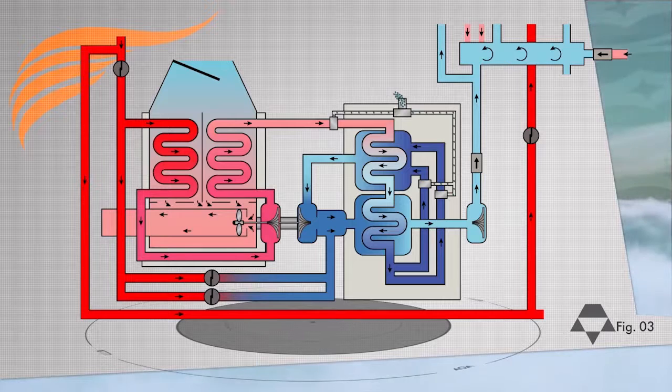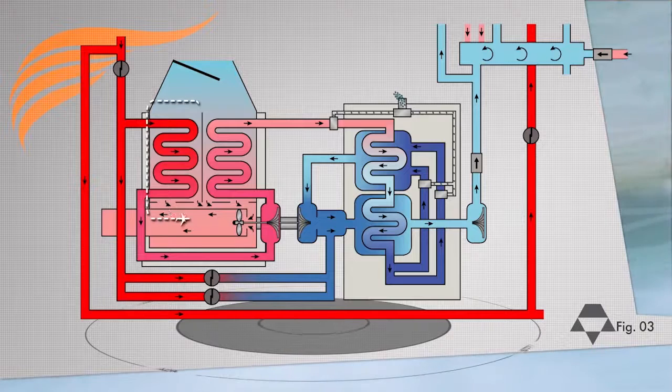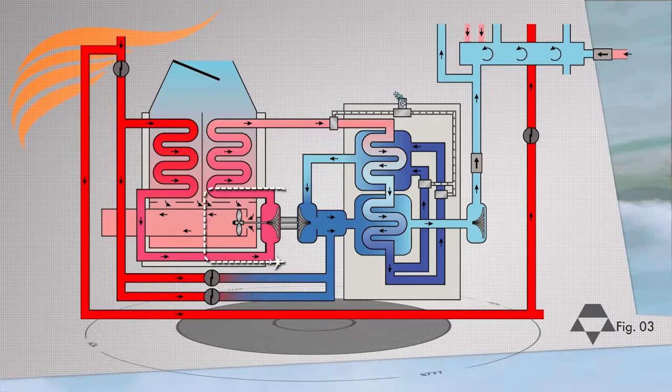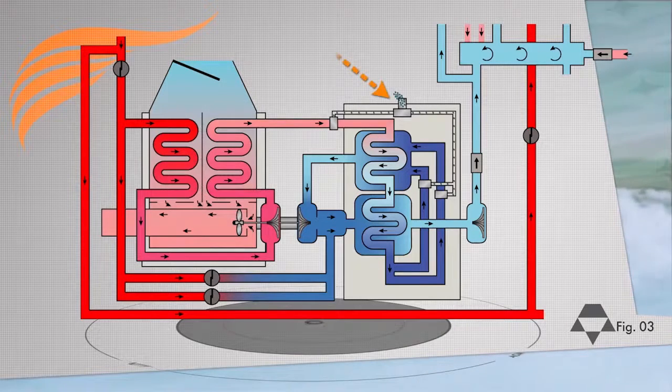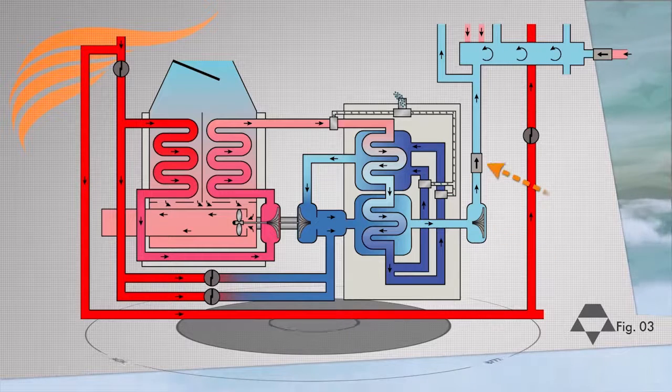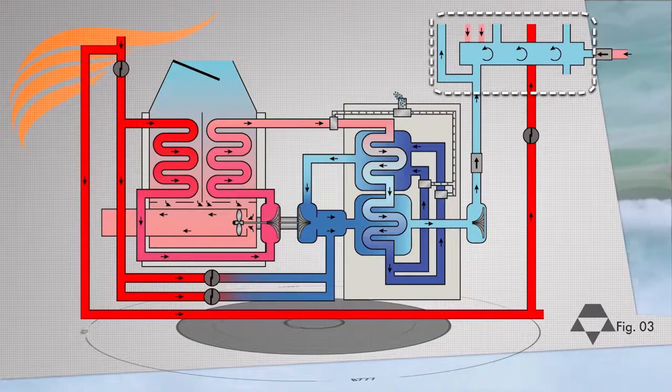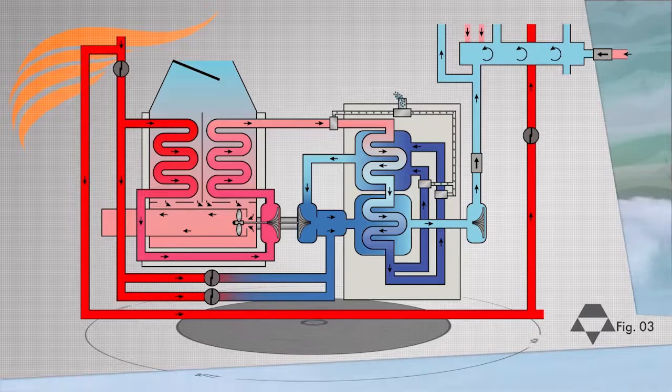The airflow control system includes the following items in the packs, in the following sequence. Primary heat exchanger, air cycle machine or ACM compressor, secondary heat exchanger, water collector, reheater, ACM turbine 1, condenser, ACM turbine 2, check valve, and mixed manifold. Air from the packs is mixed with recirculated air in the mixed manifold. This air moves through the air ducting system to the passenger zones. The flight deck receives air directly from the left pack.